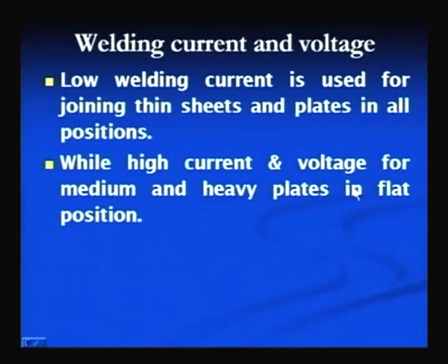However, fluidity becomes crucial in odd position welding, particularly in overhead and the vertical position welding.